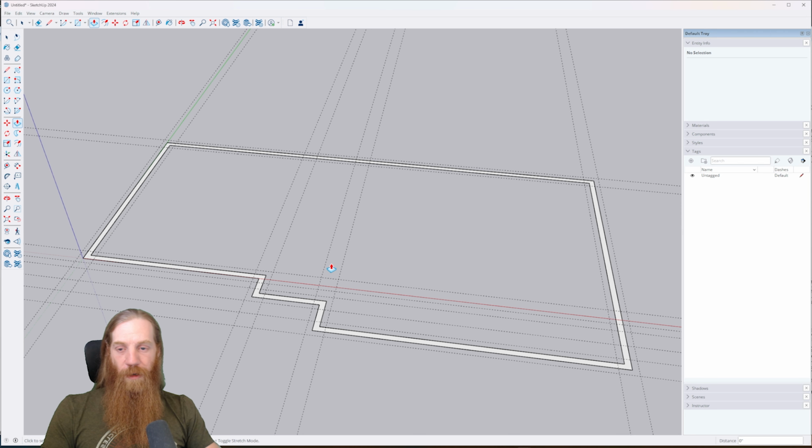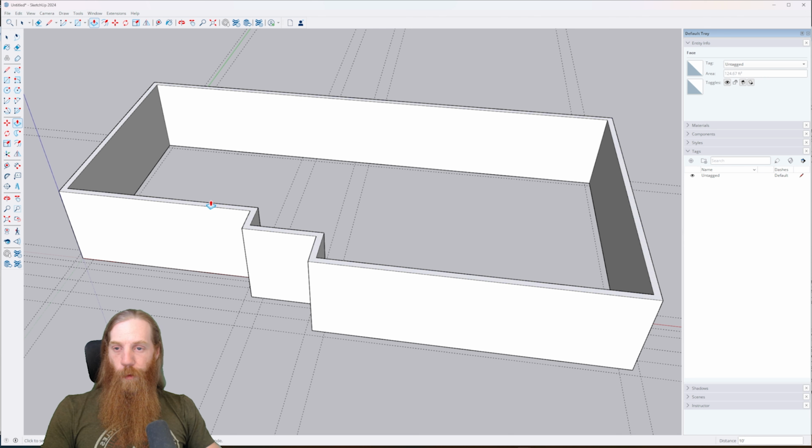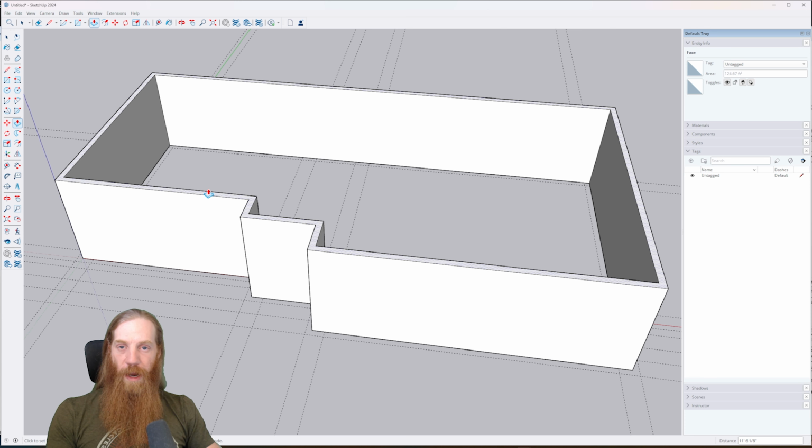So we're going to go ahead and do that. I know that this plan called for a 4-inch slab. Even if it called for something else, I would probably go ahead and go with the 4-inch slab anyways, knowing that my engineer is going to be okay with that and would probably recommend that anyways, right? So knowing that we're going to have the 4-inch slab, if we want to have a 9-foot ceiling height on top of that slab, then we need to go 9'4", right, to account for the slab height. Because our floor trusses for the floor above, which creates our ceiling for the basement, are going to rest right on top of